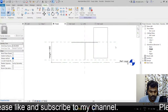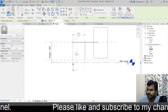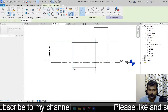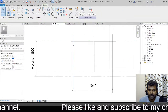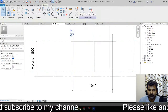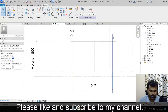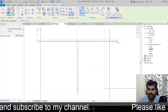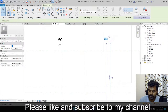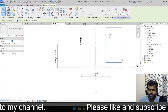So here again, let's draw a model line here and here. Let's do DI. Here I'm just going to give an offset of 50 mm. In case I give 50 mm here and here, how much will I get? 1100.